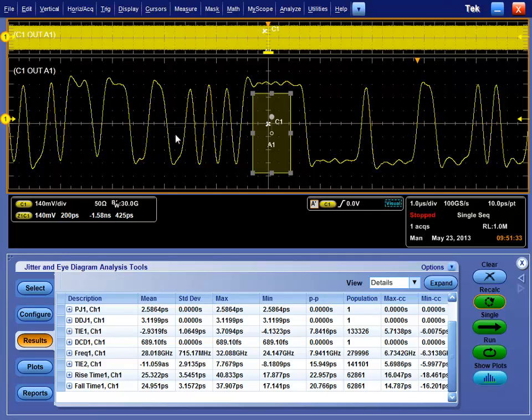The bit rate is not the thing that's going to be your limiting factor. It's the rise times. If you're doing chip characterization, you may have something on the order of 15 picoseconds or faster. You may even have a chip capable of 10. That's a screaming fast chip. If you do, this scope can still capture 9 picosecond rise times. This device under test is putting out 17 to mid-20 type rise times on this signal. I have plenty of bandwidth and capturability in this Tektronix system to debug this 28 gigabit signal.